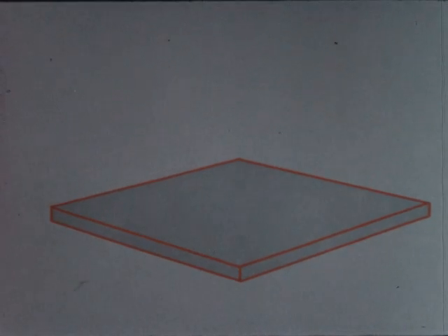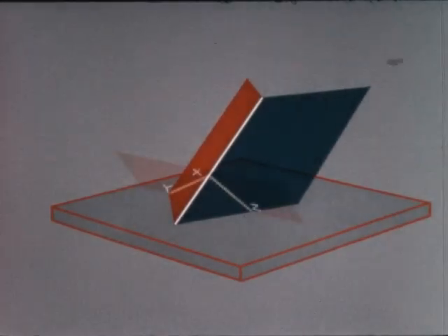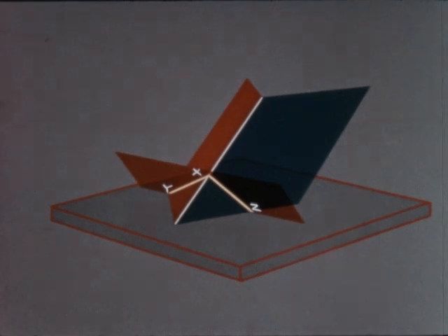We may also apply the principles of revolution to measure the true size of the dihedral angle between two planes. The measuring plane passed perpendicular to the line of intersection of the two planes cuts the lines XY and XZ from the given planes.